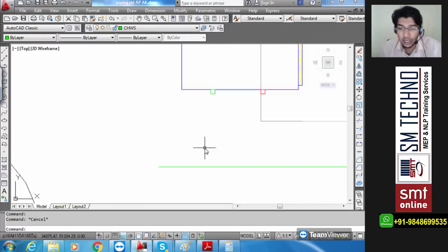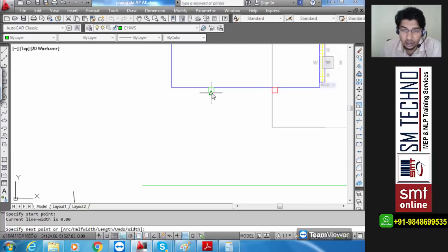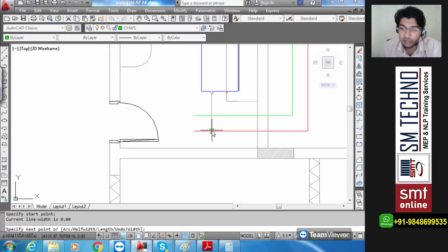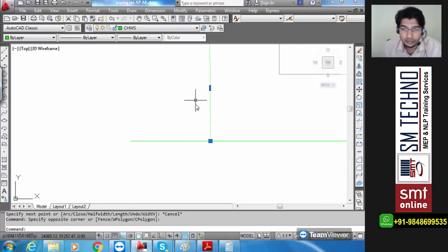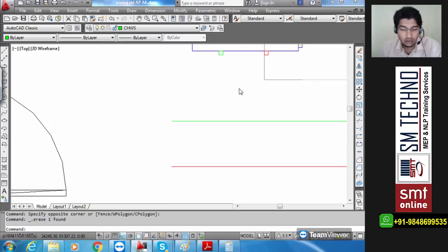Fine. So now depending upon the coloration and the indication of supply and return is where you have to join the lines. Coming back to the same polyline, from the center point, you have to go till the green pipe or the red pipe? Only till the green pipe, because till there is only the supply limited to you. It did not come straight. Ortho is turned on.